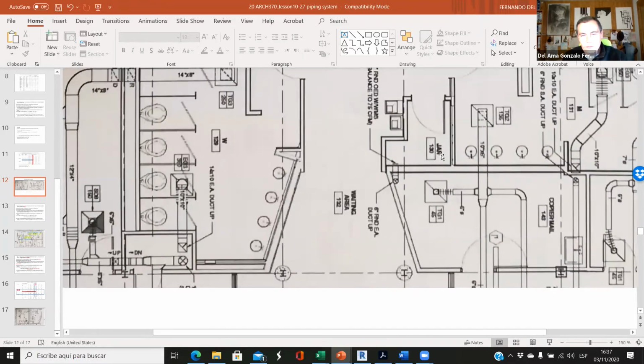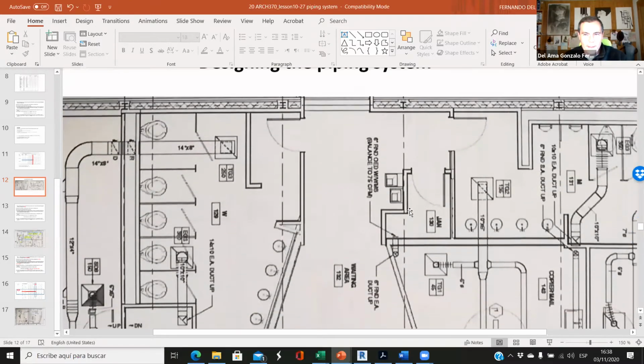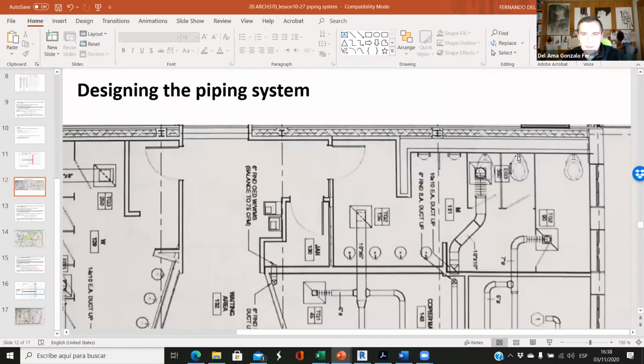Here we have this janitor room, and I'm sure that there would be some pipes in this janitor room, especially those that come from these sinks here. So I'm sure that there will be like another stack here. So in this, there are 3 toilets. We have 2 urinals. So all these will be connected to a vent stack. I think we should place the vertical stack here. Why? Because the closer to the toilets, the better. Okay, so if we have 2 urinals and 3 toilets, I would place the vertical pipe here because it's closer to the toilets. I wouldn't place the stack, the vertical one here.